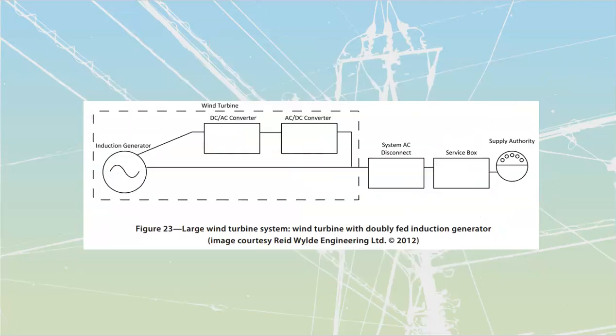There are other variations as well. There's another one that's the DFIG, doubly fed induction generator. These are very common in large power systems. That allows me to synchronize the generator at the genset without having to be electronically tied with the utility grid. It's basically going to slow the roll on the rotor itself. So I'm going to feed back in, once again, from my supply authority on the DFIG. The DFIG is going to provide a voltage signal that is going to be run to the actual windings of these things.